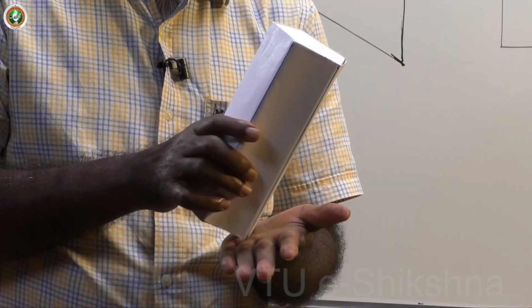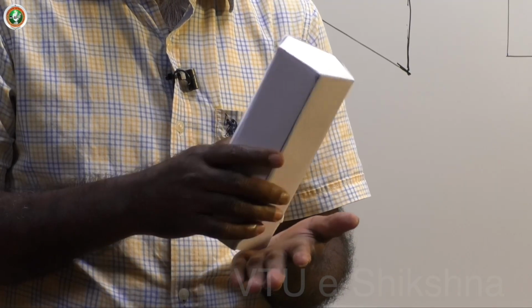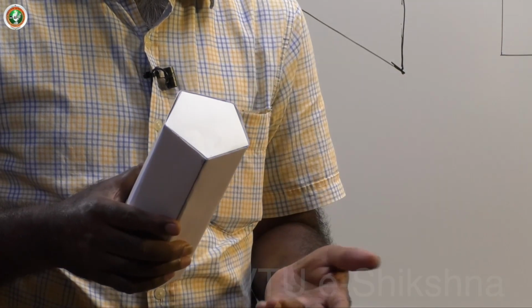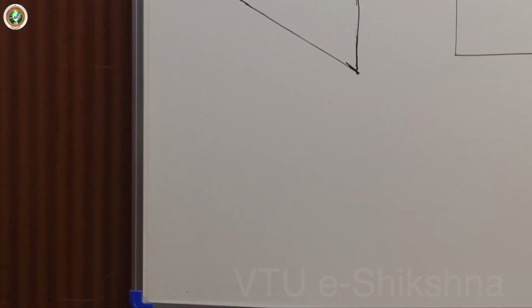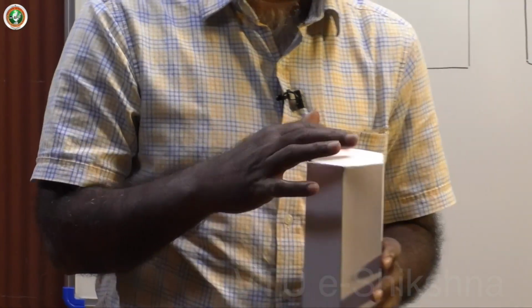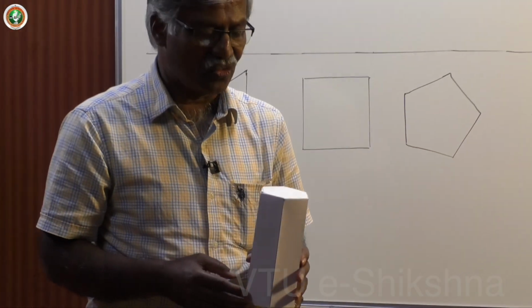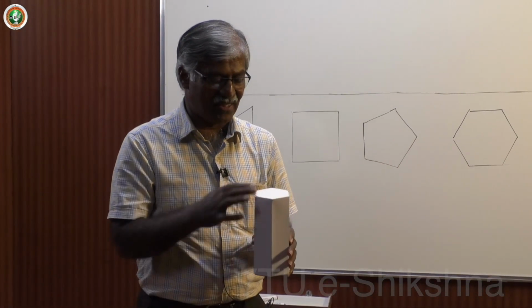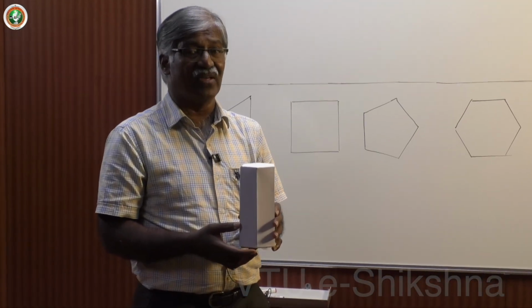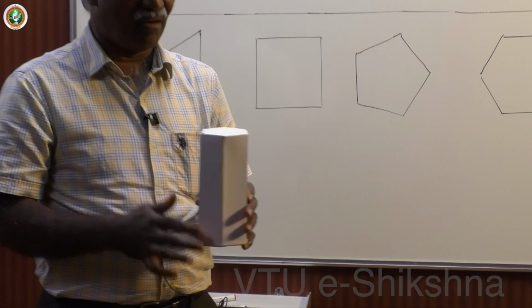So we have the base edge reference and base corner reference for inclination purposes. They may give the axis reference or some lateral surface. Now I have a hexagon, same type, top face and base. It has 6 base edges and 6 face edges, and also the axis, the imaginary line joining the top face and base centers. These are all longer edges.